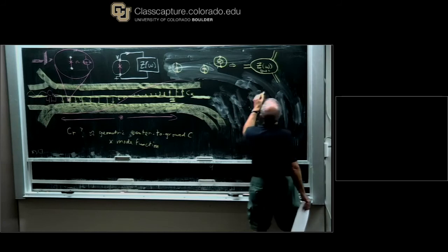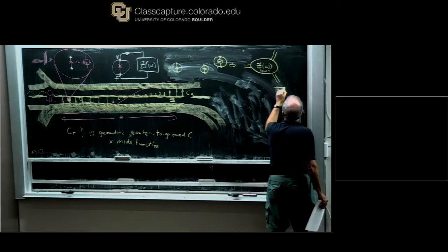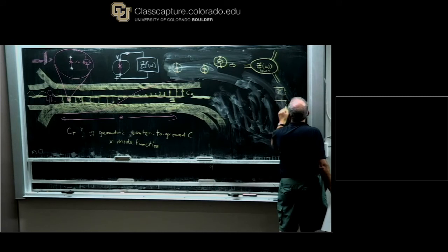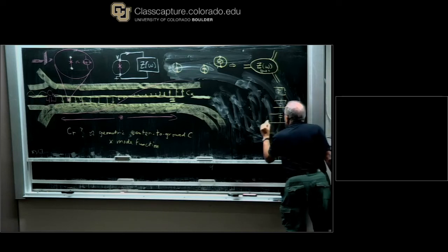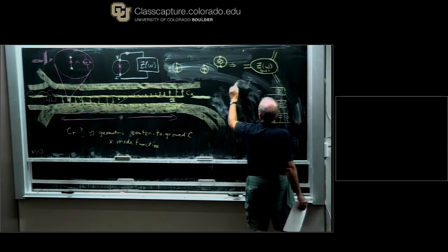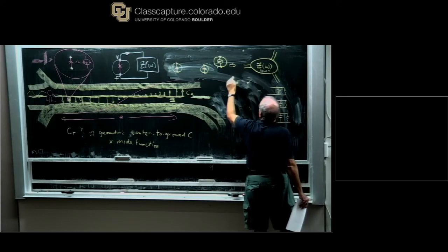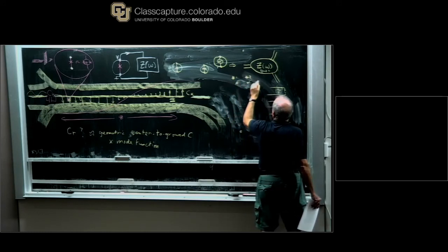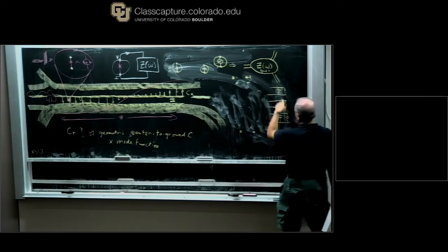And there is a Foster-like theorem for this, in which the key thing is, yes, there is a sequence of LC circuits, but you consider them hooked up in a quite different way. Again, infinitely many. But in here, what you do is you draw, well, here's port 1, the terminals of port 1. Here's the terminals of port 2, terminals of port 3. Let's stick with 2 ports. So this will be a 2-port, 3-pole model.